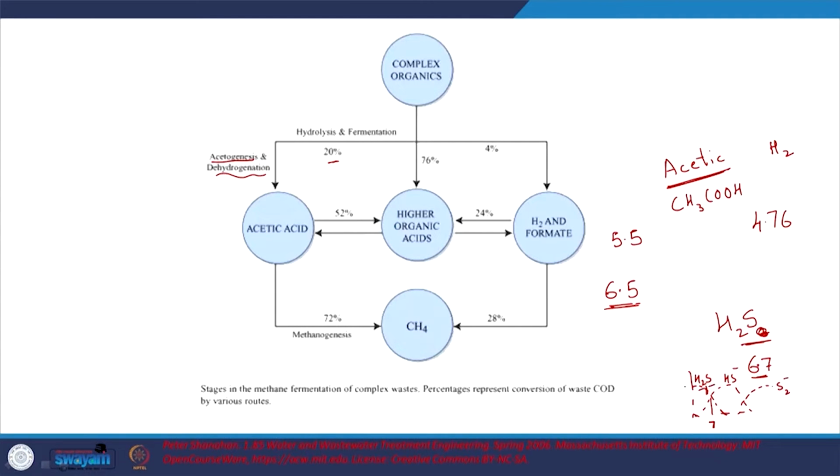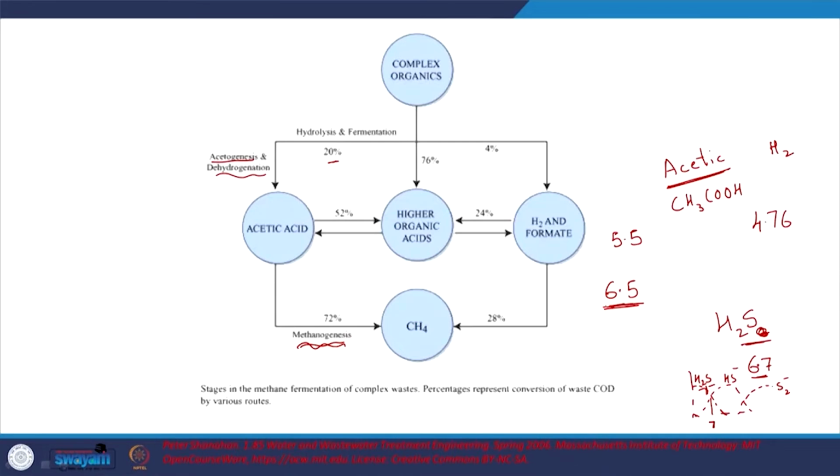So, similar to us, the microbes are very picky, right, and that is why the microorganisms, especially the ones that lead to methanogenesis, the methanogens, are called the prima donna. You need to really take great care of them. Any changes to their environment, and they will start nagging at you. So, these are the prima donnas of this anaerobic digestion process, where the pH and also the toxicity of some of the relevant products, even at very low concentration, is important.